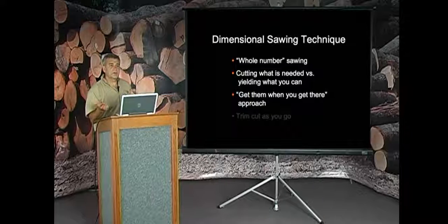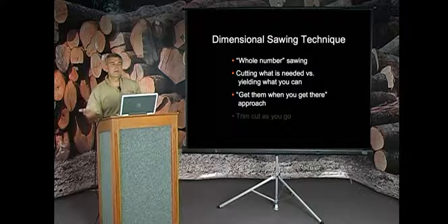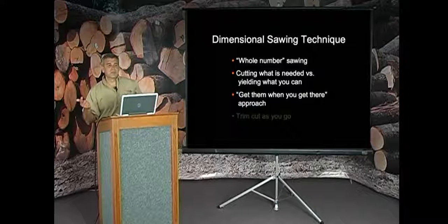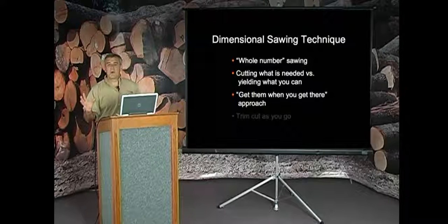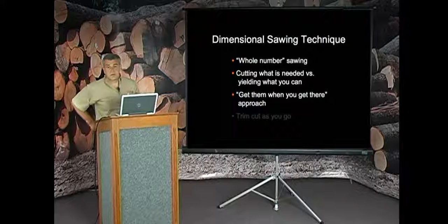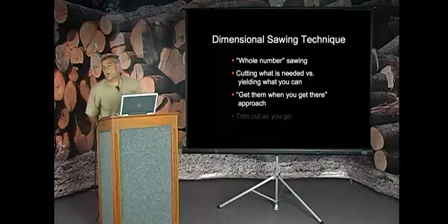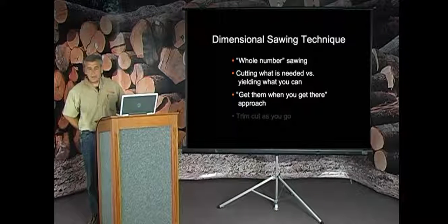Cutting all 2x6s out of a log or all 2x4s, I'll guarantee you, you are not going to yield that log as well as if you need multiple dimensions. You need some 4s, you need some 6s, you need some 8s, because all logs are not built to make you one specific product. And you're going to yield a lot better if you cut for yield versus the specific need. And I know you get on saw jobs and the guy says, all I want's 2x4s. And you know what? That's what you do.